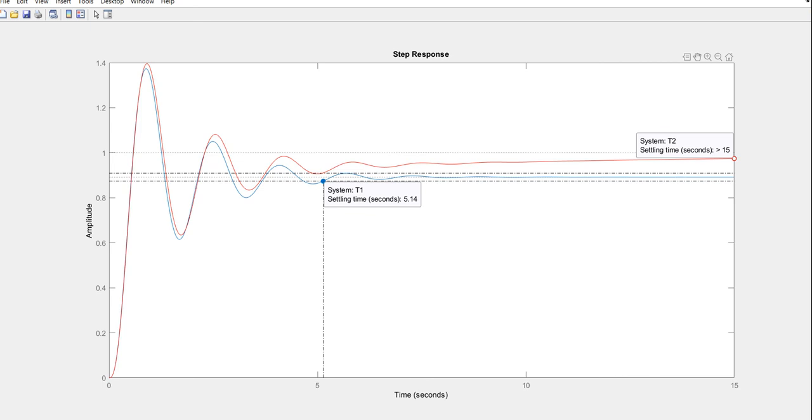In other terms, by the introduction of the PI controller, the step response of the system has become quite slow. So it takes a long time for the system to reach its final value. And that's not a nice property. Indeed, we don't want to have our system acting so slowly. Okay, we want it to be quick.